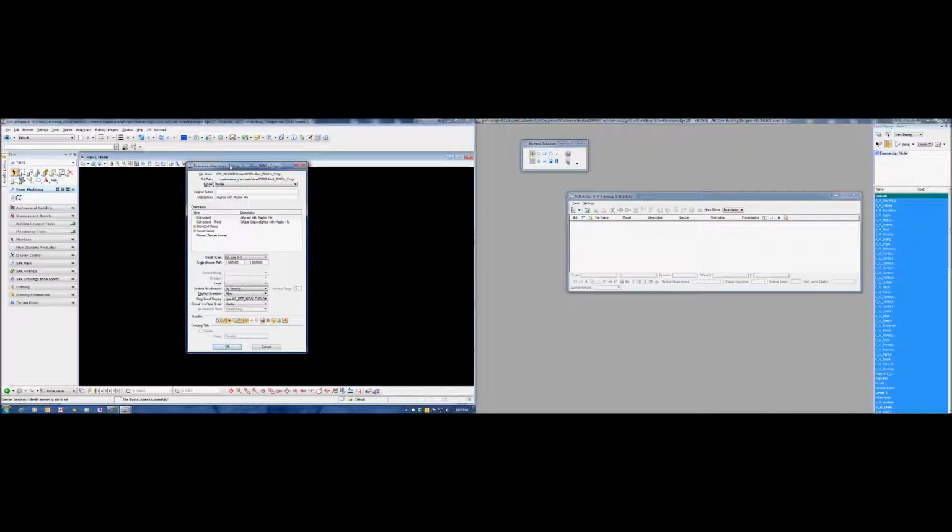So under this dialog box, we want to make sure we're using the extraction that we want. So grab the extraction submodel that you want to use and come in down here and select coincident. Next thing is make sure this is set to 1:1.